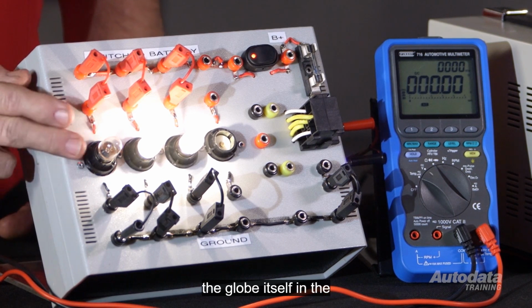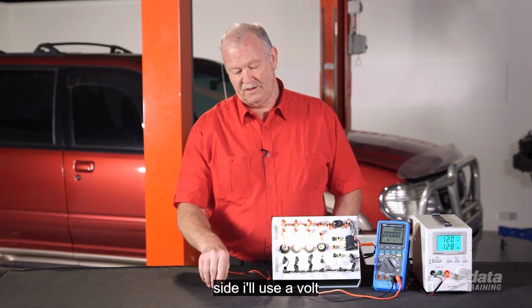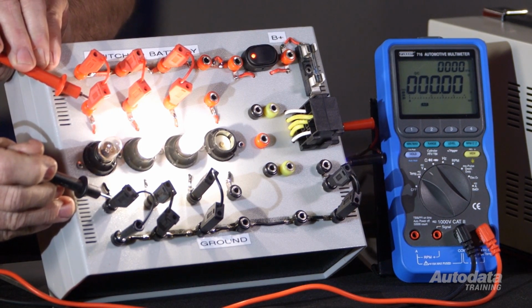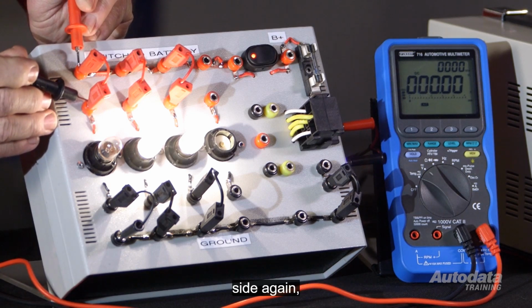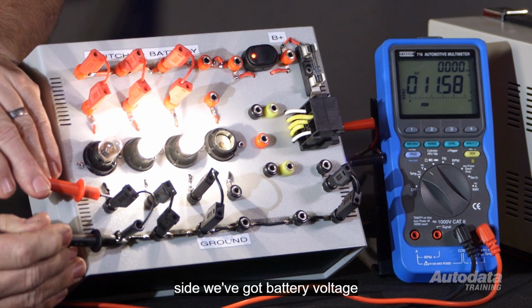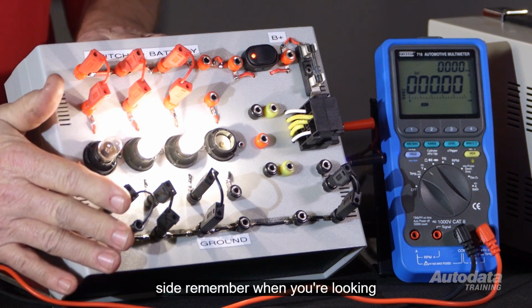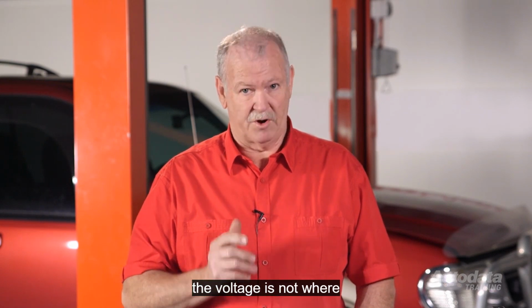The fault could be in the globe itself, in the positive side, or the negative side. I'll use a voltmeter to check my readings. Across the globe, 0 volts. Across the positive side, again 0 volts. Across the negative side, we've got battery voltage. That indicates that the open circuit is on the negative side. Remember, when you're looking for an open circuit, you're looking for where the voltage is, not where it isn't.